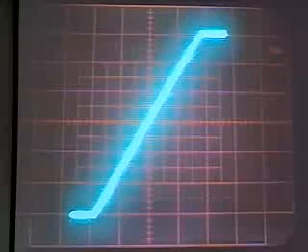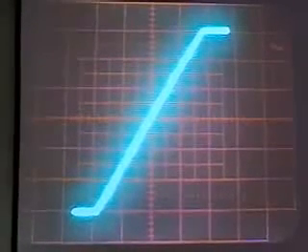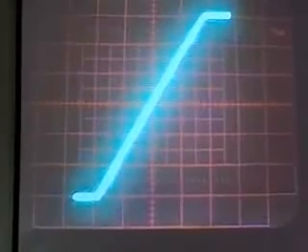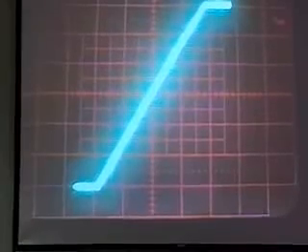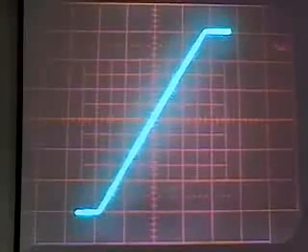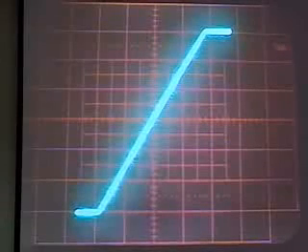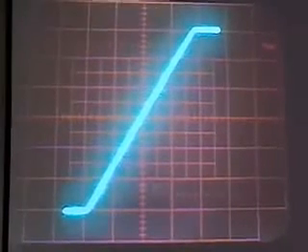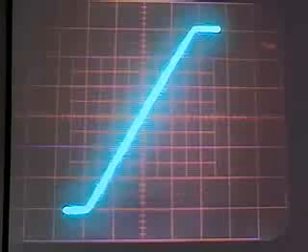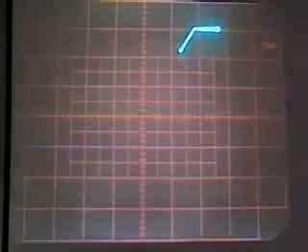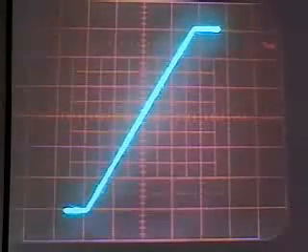So what I'm going to do now is hit the op amp to the wazoo, and this isn't going to change, because it's my external resistors that control it, independent of the value of A, provided A continues to be very large. I'm just articulating the Vout, Vin curve, and let me start hitting the op amp. Notice that it's pretty stable. It doesn't change because it's independent of the amplifier values.